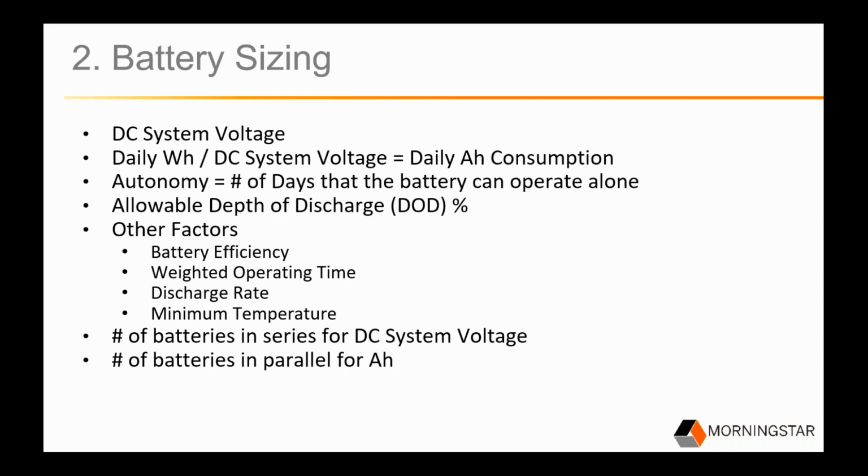There are several other factors that need to be taken into account when sizing the battery bank, including battery efficiency, weighted operating time, discharge rates, and minimum temperature.